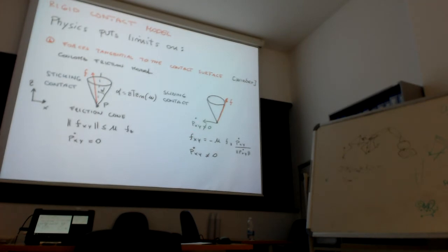In this case, we said that the Coulomb force remains constant, and the contact force is only the Coulomb force. We discard the viscous effects, and the force direction lies on the cone, opposite to the direction of slippage. So we have this definition: the tangential component is opposite to the velocity. This is the direction of the velocity vector during slippage. We don't care about this. We mainly talk about this in this course. So we call it friction cone constraints.